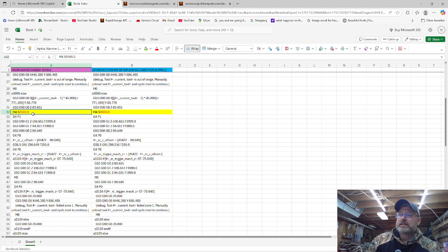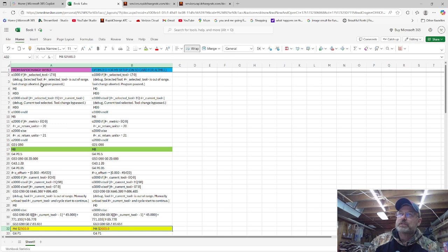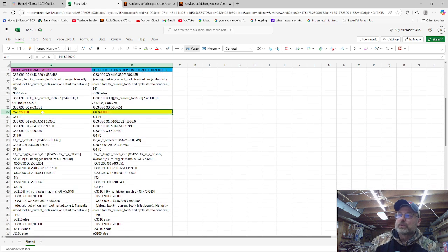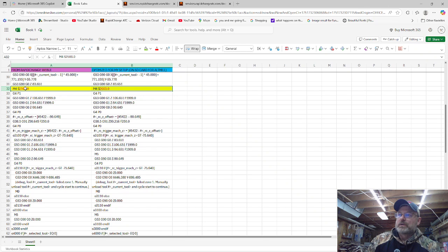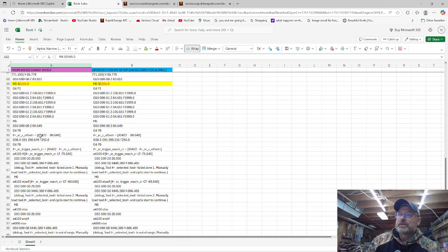So when I set up my macros in G-Sender, this is the tool change macro is what this is. Sorry if I said post processor. This is your tool change macro. And so when you create your macros, you're going to set your pickup speed, which is down here at 2100, is what I set mine at.